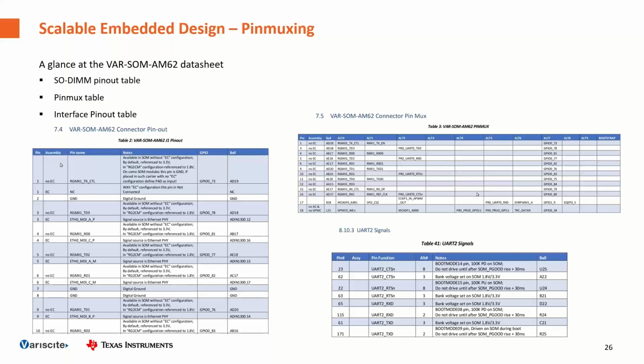If you look at pin 3, in case of no Ethernet controller, you have the ball AD18, but if you use the SOM with the PHY on board, that specific pin 3 of the connector will expose pin 12 of the AD18 chip. And this is just a reference example. If we check every pin, you will see that there are some alternate functions that allow you to have different options for the same pin.